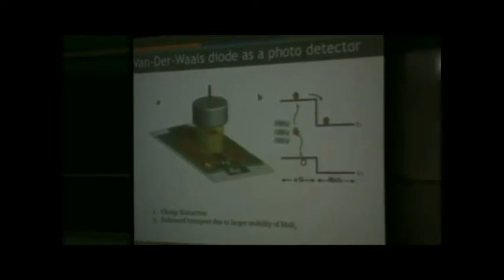Now, if you look at the imagers that we use in X-ray imagers and others, for large area application, doping is so expensive that people don't dope it. People just use a metal semiconductor junction to collect light. So we said that, okay, now if I can create a PN junction like this just by putting MoS2 and amorphous silicon, I can use a built-in field here to collect the light and separate the carriers.